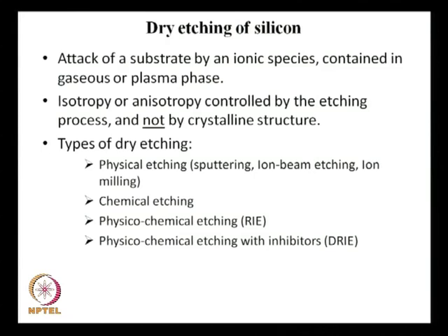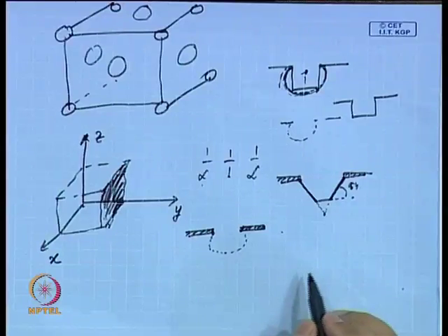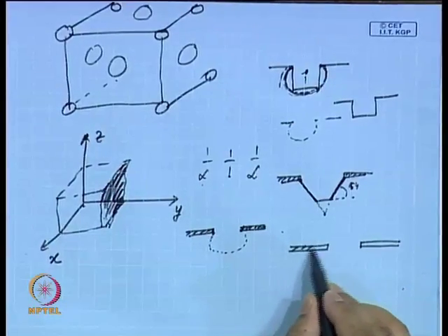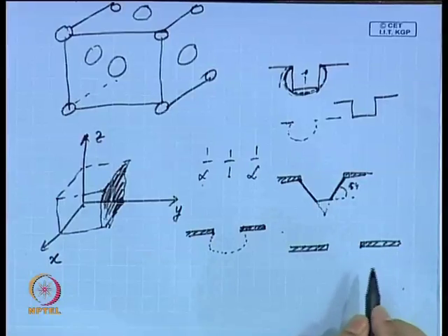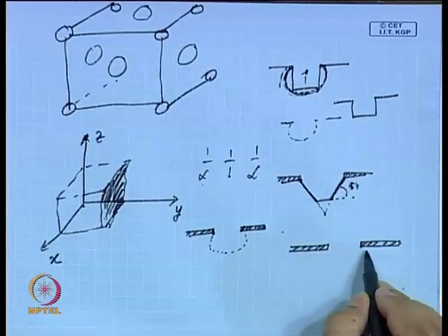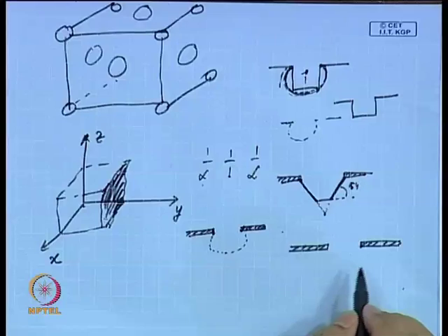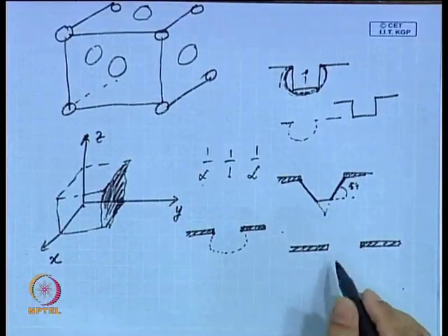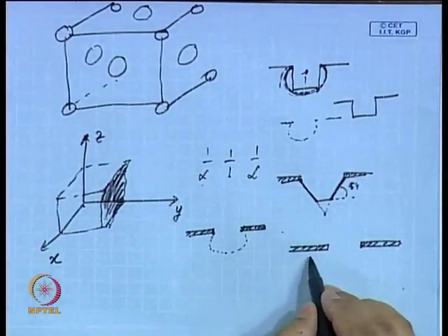So, what you do here is, suppose this is the portion which is protected by mask. Now, this portion is exposed, so it is bare silicon. Having bare silicon is a little difficult, because the moment you keep it in oxygen, a very thin layer of silicon dioxide forms on this layer, but this can be etched out fast, but there would be a very thin layer of SiO2. Now, that is probably not the point. What I make here is, this is a bare silicon.